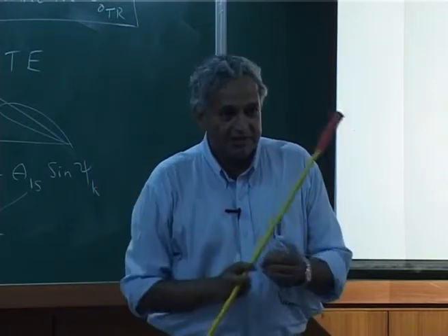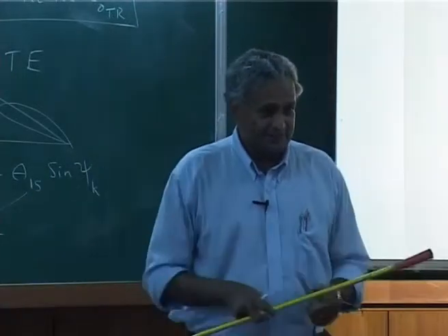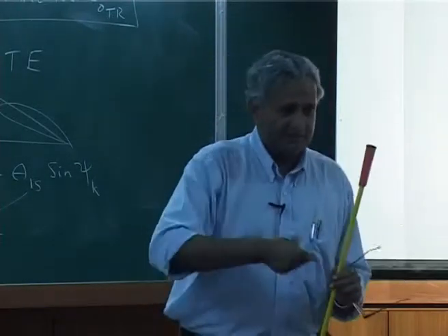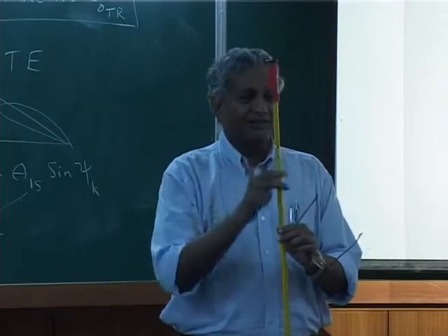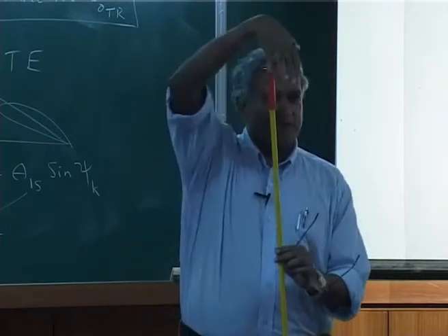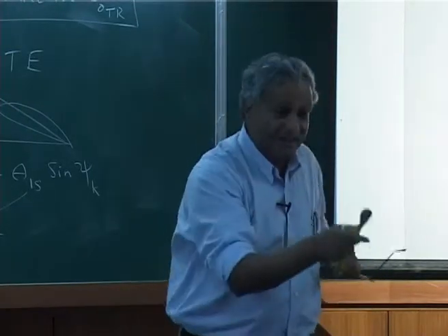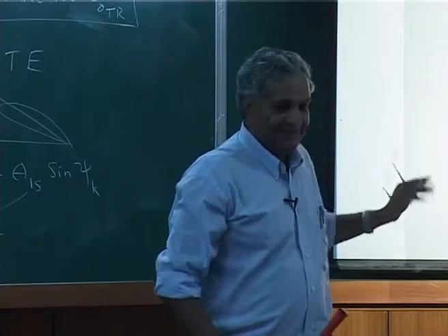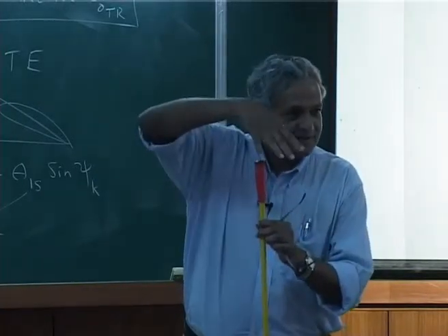Flap is completely restricted in a propeller. You have a propeller blade in an aircraft. It is very rigid, you attach it, bolt it. Then it is rotating. If you want to fly forward, it will not tilt like this. You have to tilt the entire shaft. In a helicopter, the shaft is not tilted, only the rotor disc is tilted.